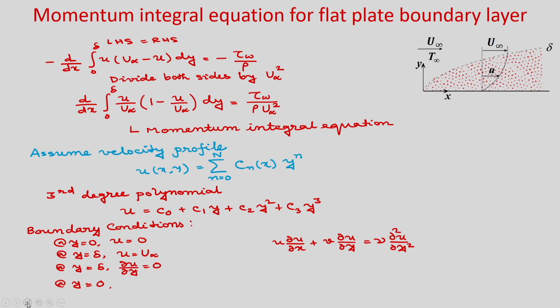So, this is your boundary layer equation. Now, you put y is equal to 0, what happens? Okay. So, we will derive this boundary condition. So, at y is equal to 0, u is 0, and at y is equal to 0, v is 0. Okay. So, you can see the left hand side 2 terms are 0. So, you will get del 2 u by del y square is equal to 0. Okay. So, this is your derived boundary condition.